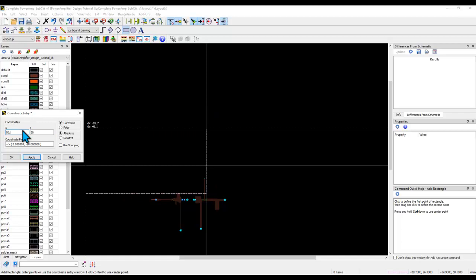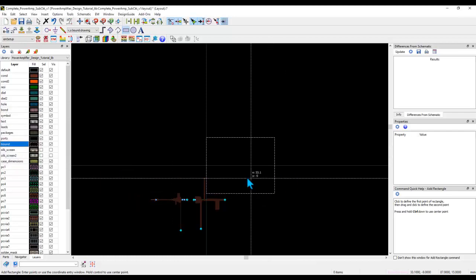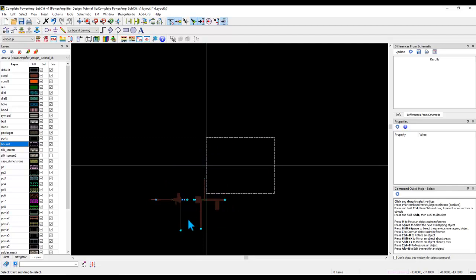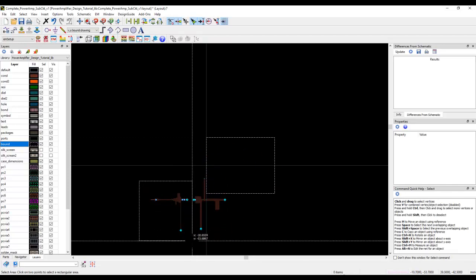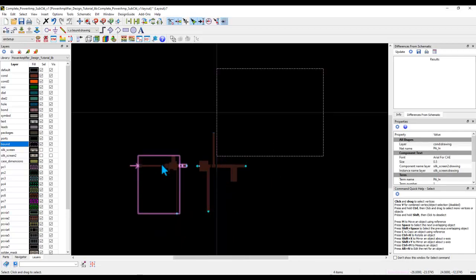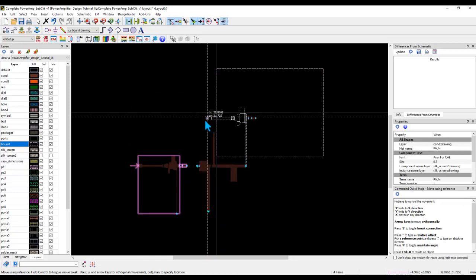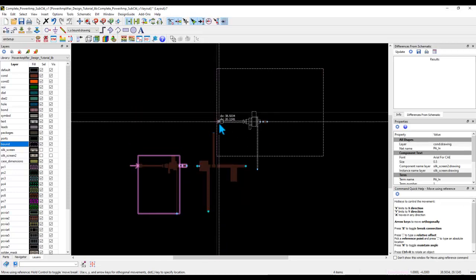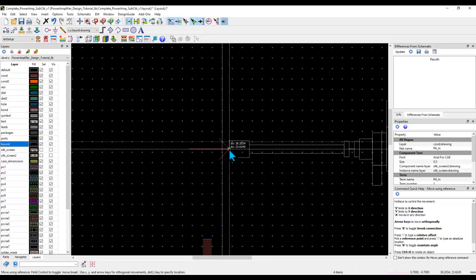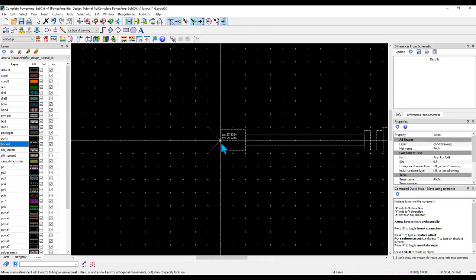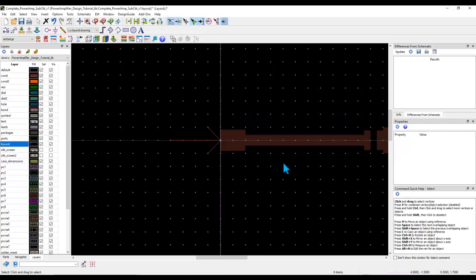So typically I'm going to specify that as 50.8. So now that's my 2 inch by 40 kind of PCB in which I would like to assemble my PA. So what I'm going to do here, I will take the input section, I will click on move and this input feed point I would like to place in the center, and as you can see the center currently is on origin because that's how I designed the overall box dimension. So I can place it at 0 0.